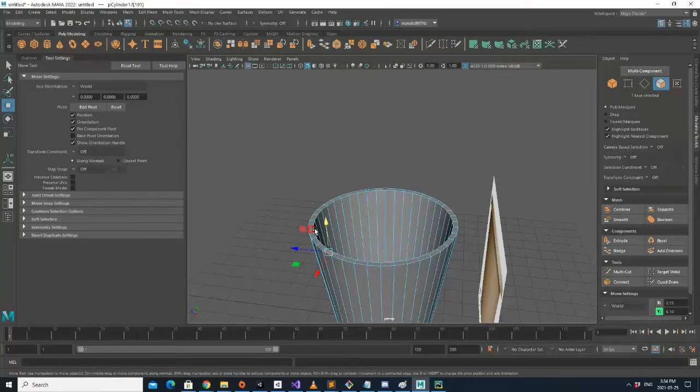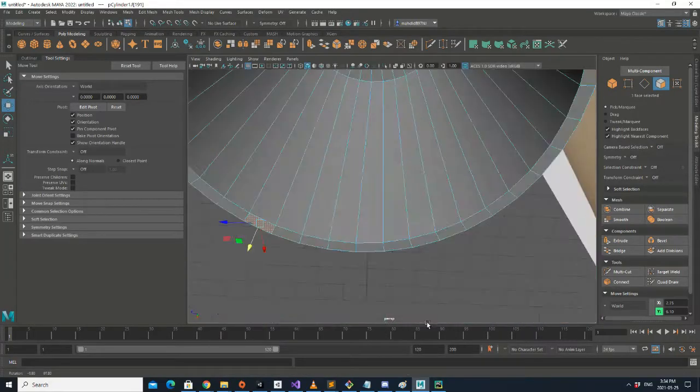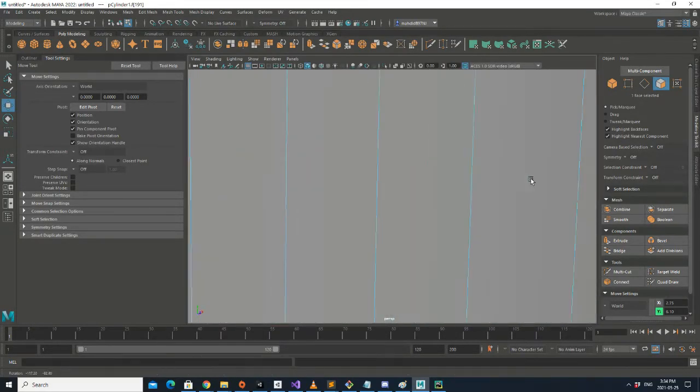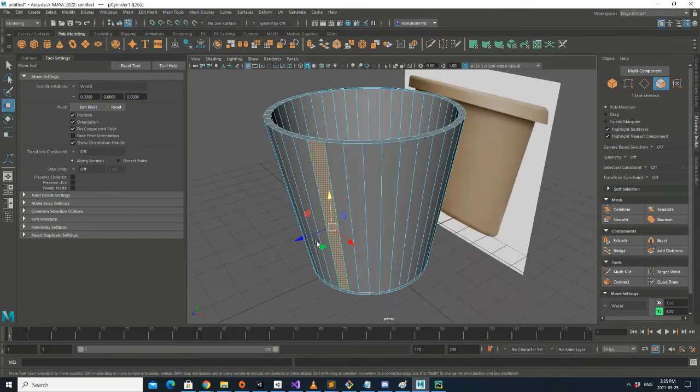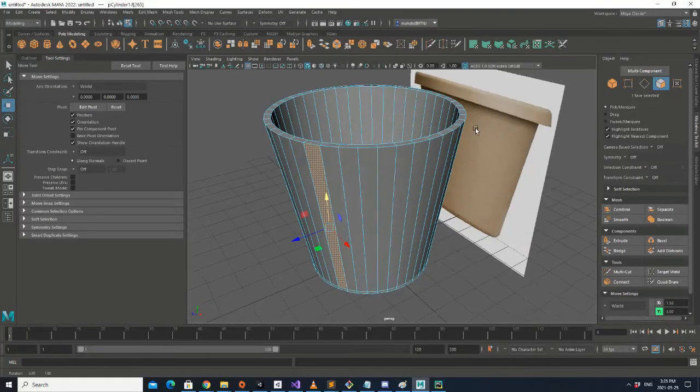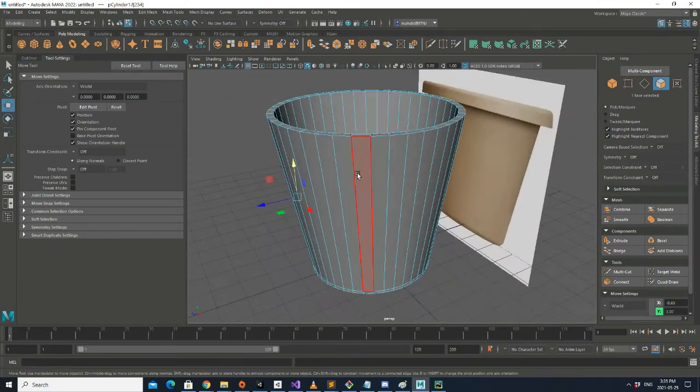Moreover, if you import your model into game engines, for example, you will see that it has some walls around it. But if you go into your model and look outside, you will see no walls, because faces have normals, and models are rendered by the normals. If you go behind a face, you cannot see it and you can see through it. So it's important to have all the inner and outer faces.